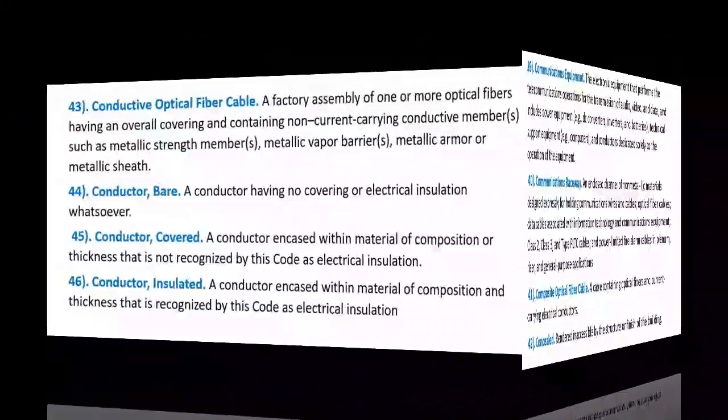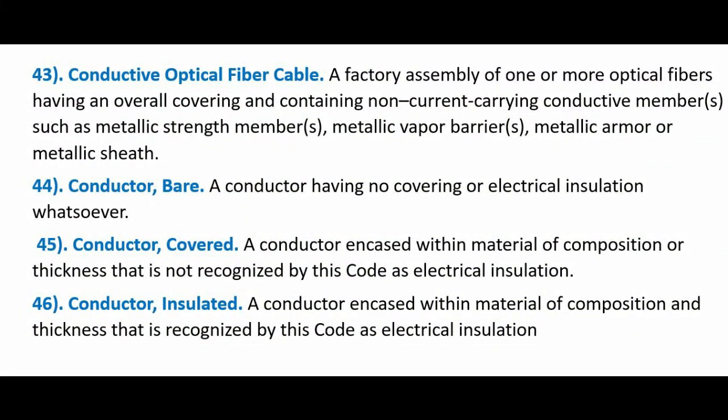43. Conductive optical fiber cable. A factory assembly of one or more optical fibers having an overall covering and containing non-current carrying conductive member such as metallic strength member, metallic vapor barrier, metallic armor or metallic sheath.